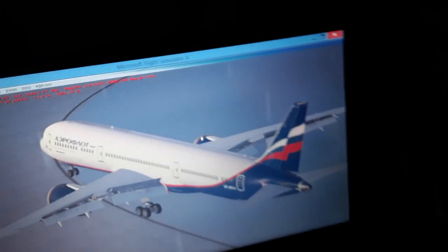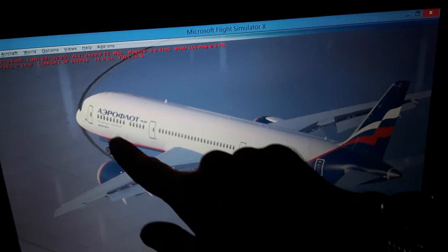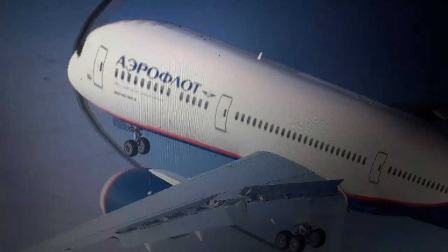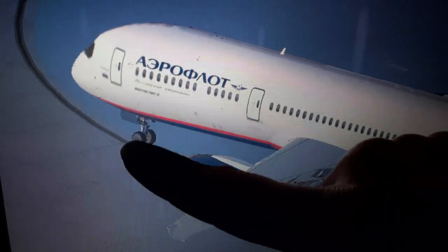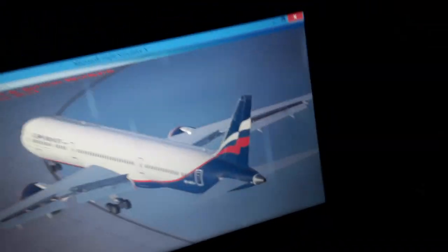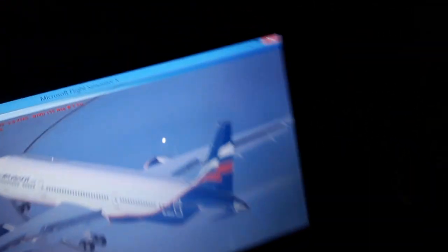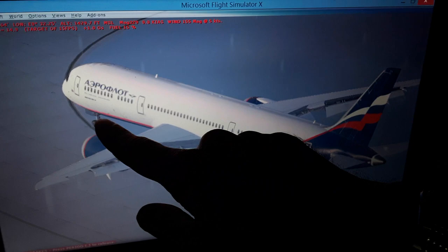So we have the nose wheel. It decreases the forward nose wheel over here to 7.6 degrees up to 70 knots. Then it deactivates, it locks to 0 deflection. So we have only the rudder aerodynamically effective because we don't need the nose wheel above 80 knots or 144 kilometers an hour.